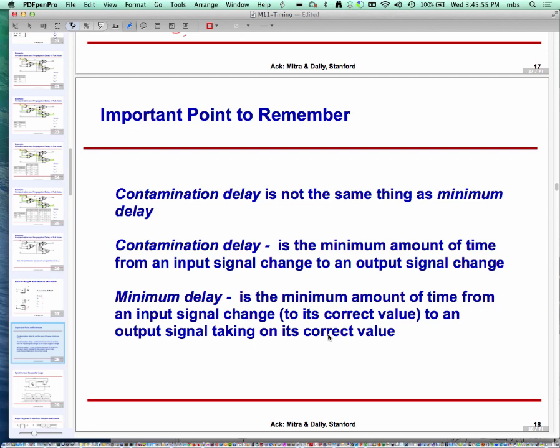The other thing that happens is that when you make chips, they are not identical, because the transistors are fabricated using chemical processes. So two copies of the same chip actually have different delays. The manufacturer may say the delay of this chip may range from 100 to 120. What that is really saying is that propagation delay can range anywhere from 100 to 120. Contamination delay is often also specified because it's also needed. We'll see how it gets used.